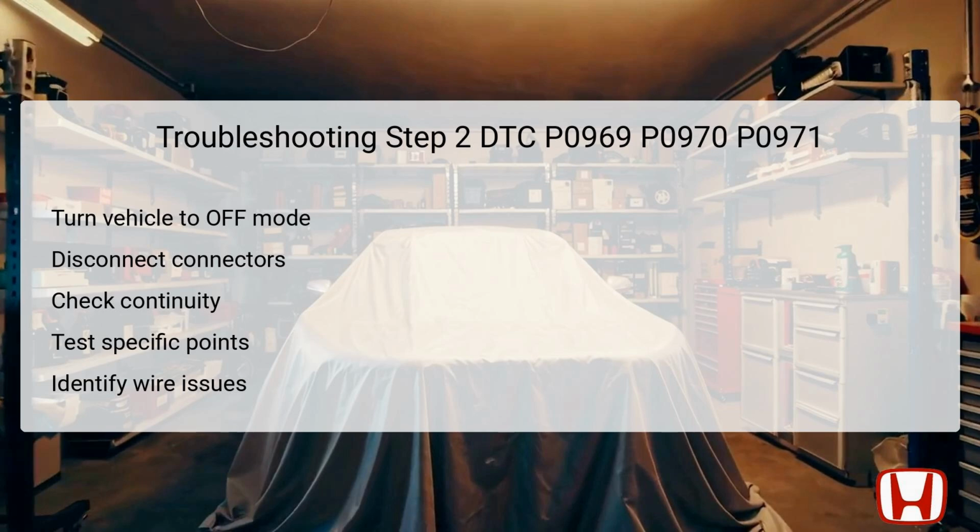Following disconnection, continuity between test points is checked. These test points include select pins from each connector. This step assesses whether the electrical paths between the solenoid and the TCM are intact. If continuity is confirmed, then the wiring is not open, leading towards further diagnostics.